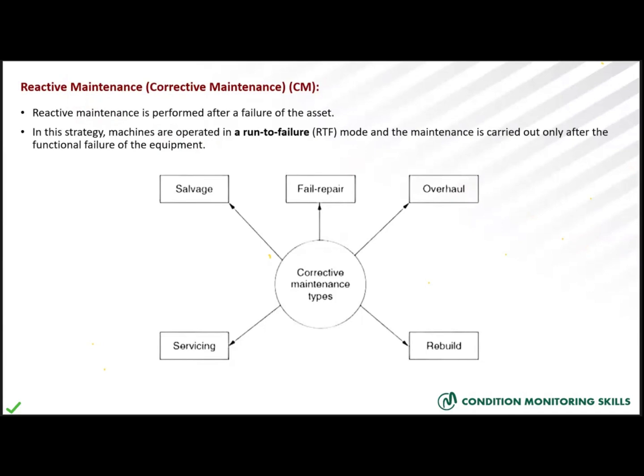The actions here are repairing, replacing faulty parts, servicing, overhauling. All of these are the actions of corrective maintenance. This type of maintenance can save money for non-critical equipment, where the breakdowns do not cause very big problems. So it is not a bad type of maintenance or a bad approach. It works for non-critical equipment.